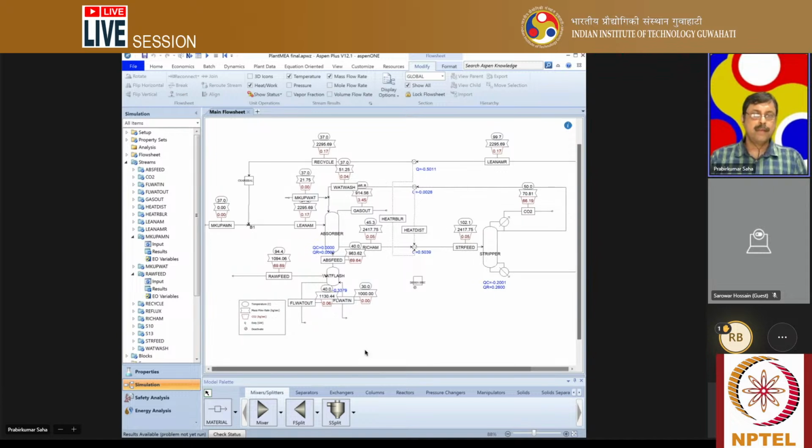So you can see the carbon dioxide in kg per second. We have 69.69 kg of carbon dioxide per second going in through the raw feed, out of which 66.19 kg per second we are able to recover. So our system has been optimized to 95% CO2 recovery.